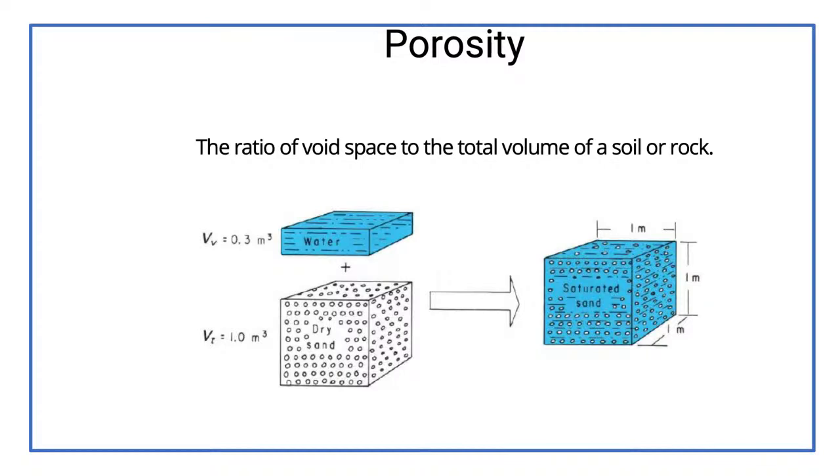We can dump that water into the sand, and you will then have a saturated sand, just like an aquifer. And 30% of that space in that cubic meter is going to be taken up by water that's going to occupy the space in between the sand grains. That is our porosity, so that is the maximum amount of water we can fit in there. In this case, it's going to be 30%. That's going to vary depending on the type of aquifer and the aquifer conditions.